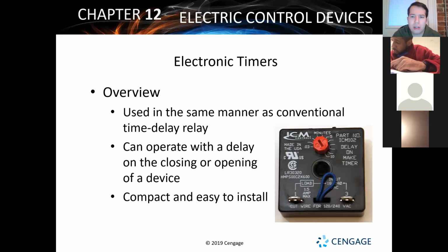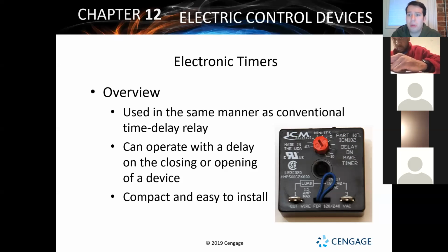The whole idea behind the time delay, and the benefit of it, is that it's going to stop us from turning on a unit over and over and over again. It's going to give the unit a break. It's going to force the system to wait a certain amount of time. Typically, most are set between 3 and 5 minutes. Typically. I don't say always, I say typically.